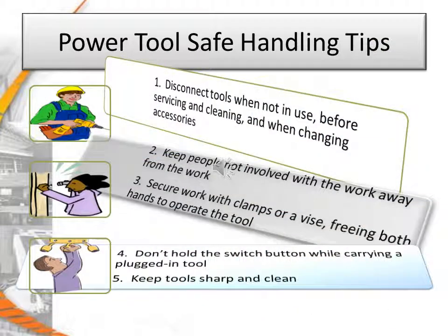Keep people not involved with the work away from the work. Secure the work with clamps or a vise, freeing both hands to operate the tool. Don't hold the switch button when carrying a plugged-in tool, and keep your tools sharp and clean.